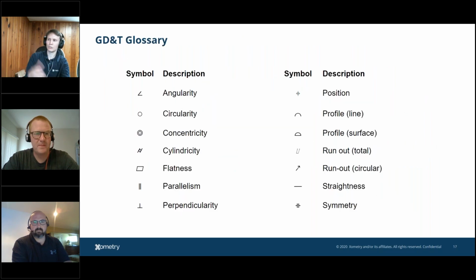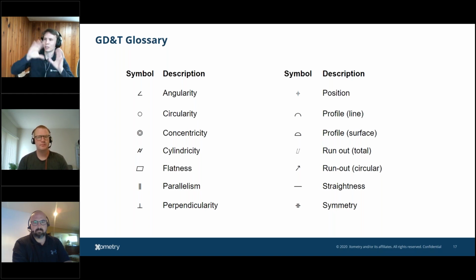And I just want to say also, when we talk about datum A, B, and C, what is so great about using datums, even in a lot of regular drawings, is that those datums are how we're setting up the machine setup. We are planing datum A to make sure that it's definitely flat, and we reference everything off of datum A. The machinist uses it as a reference, you're using it as a designer to reference all your dimensions, and our QA team, those inspectors, are referencing it as well.